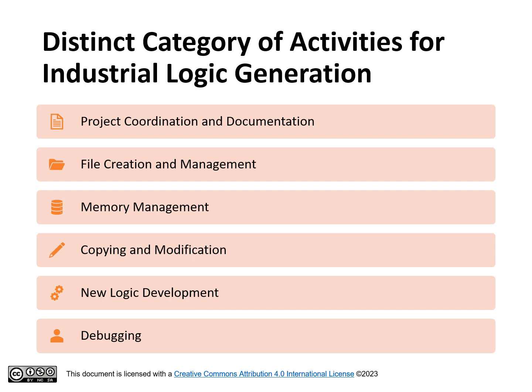New logic development. In some instances, such as the need to implement new control functions, an additional rung of logic must be developed. After the creation of the new rung, contacts and coil, logic verification, and memory map checking follow.